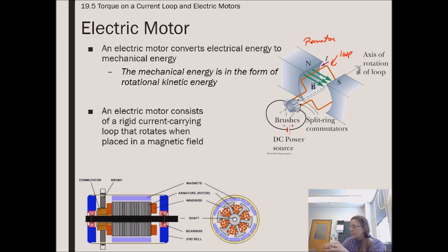Then we also have motors that are the other way, and this motor would have brushes. I don't know where the brushes went, but you can see the windings in here. They're not the nice square, but they're just wound up, and I'll pass these around in class. And then on the inside of here you have a magnet. You can tell that because when I get this thing close, it wants to stick. So if I get it shoved in there right, the thing turns on the inside. And so you can kind of see it turning on the inside, that those are the coils turning on the inside of the magnet. So that's exactly what we see here in this diagram of the motor.